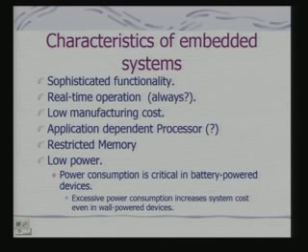Also, when we do not have battery operated devices, that is wall mounted devices powered from direct power supply, then power consumption becomes an important issue, because I need to do a heat management, heat dissipation design for those devices, which can add on to the cost of the embedded system.